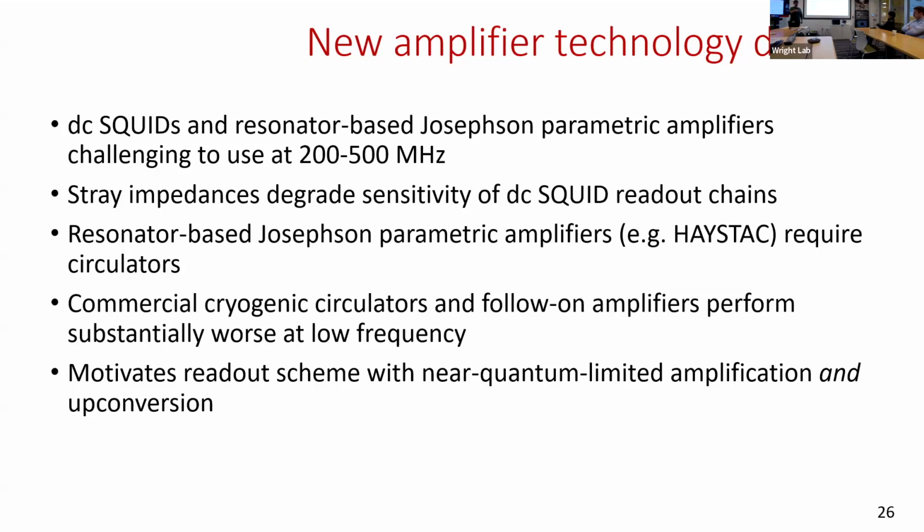There's a similar story there about the follow-on semiconductor amplifiers too. You can get a HEMT now that's 5 or 6 times the quantum limit at 6 gigahertz. But then when you look at 200 megahertz, those HEMTs are 160 times the quantum limit. So this picture here motivates